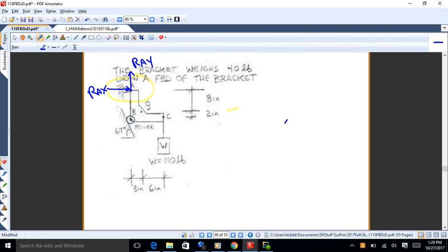Okay, how about that roller at B? Everybody just think about that for a second, get the force on that. You can kind of guess at the reactions. You got the weight there, and also the weight that goes through the center of gravity. So my guess is that roller force is going to push up, right? But if I guess wrong, if I had it going down left, it'd be okay. I'd still get the right answer when I ran the numbers. You can flip the direction and you're okay.